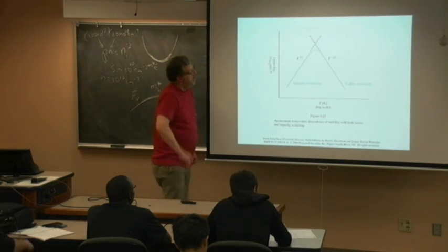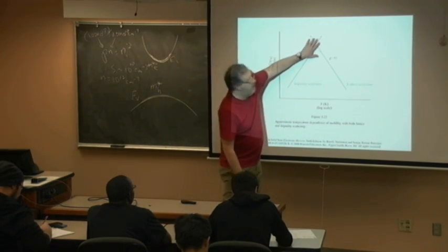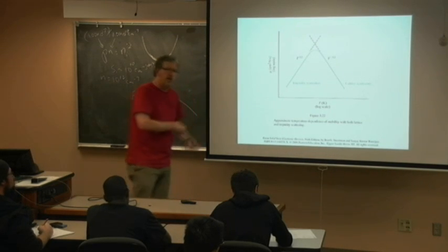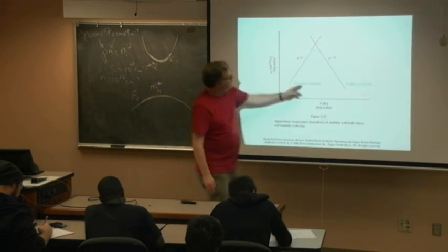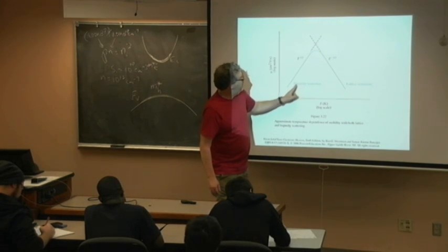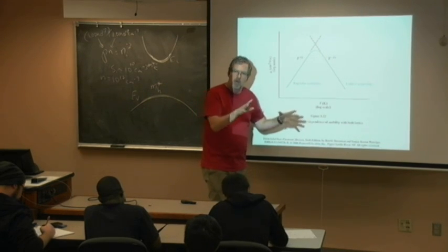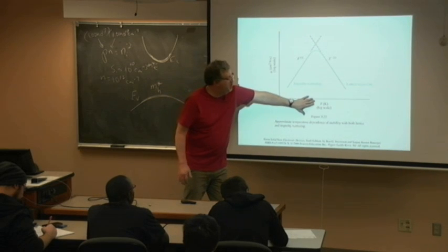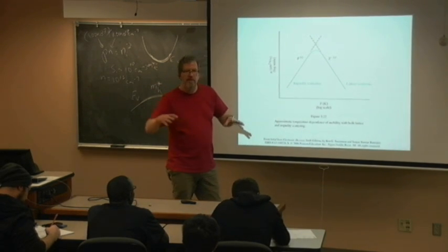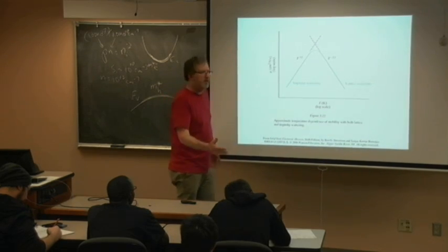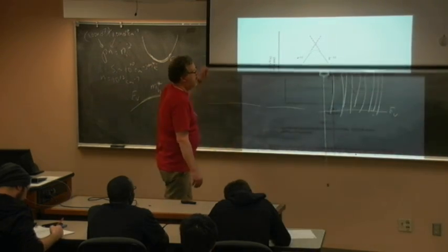Right. But then I get the impurity scattering, those little defects, those little point defects, the doping, all these things. And so as they get cold, they move more slowly. And as they move more slowly, they're influenced by these perturbations in the crystal more dramatically.